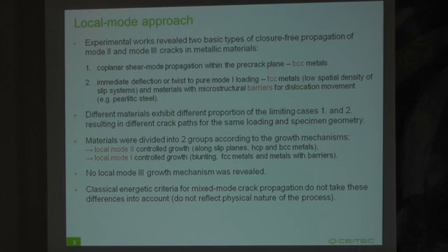So for the purpose of quantitative description of Mode 2 effective thresholds, we divided the materials into two groups, where the crack growth is controlled by the local Mode 1 mechanism and local Mode 2 mechanism. And no local Mode 3 growth mechanism was revealed. So this is what classical energetical criteria for mixed mode crack propagation do not take into account.